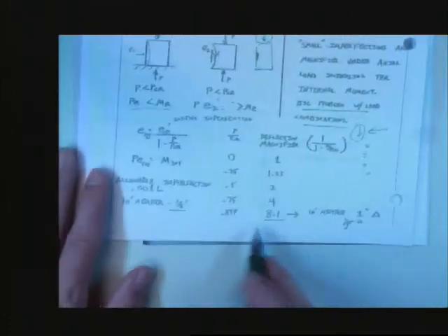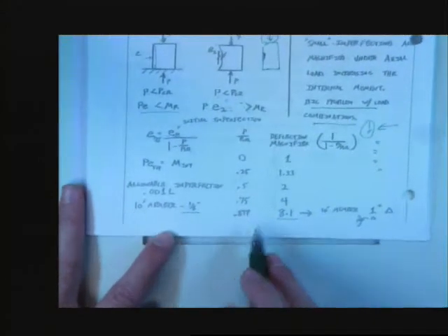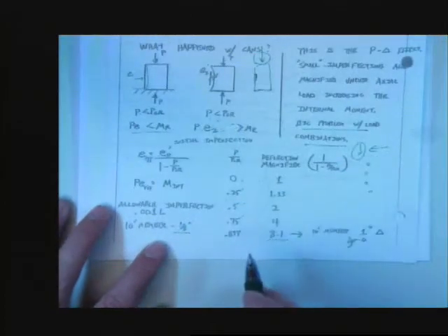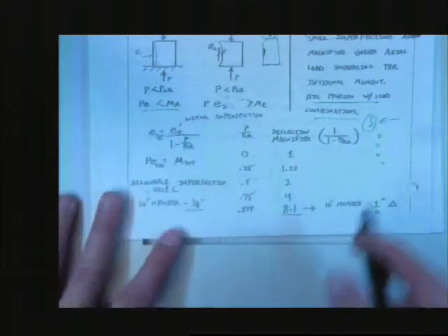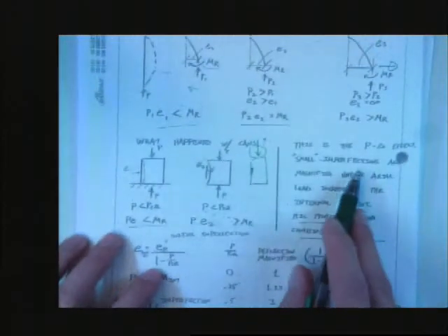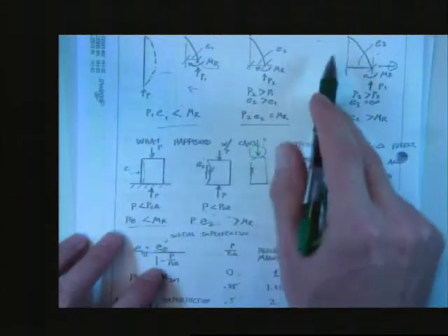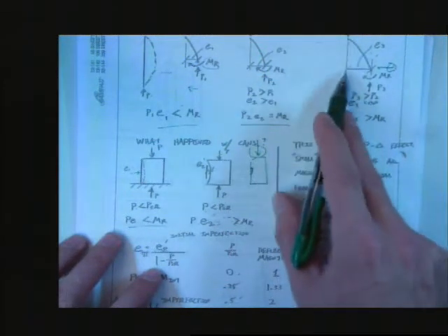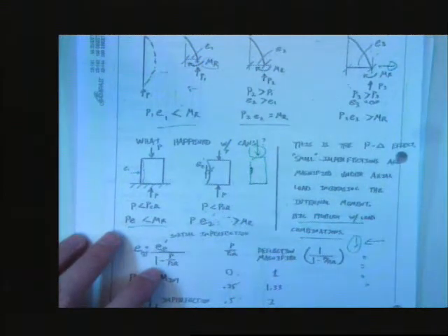Okay, great. That's what the P-delta effect does. It magnifies any imperfections. It also magnifies things if you have horizontal and simultaneously axial load. It's not that big of a deal. There's all kinds of ways to take it into account. What you really do is an iterative approach where you put some axial load on it, some horizontal load on it, more axial load, more horizontal load, and those things will magnify. Those things will add to one another. Okay? That's what you have to do.